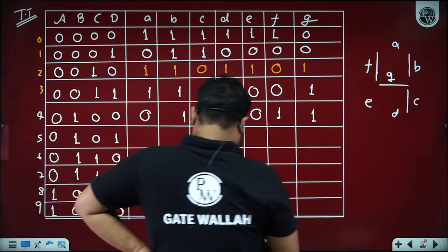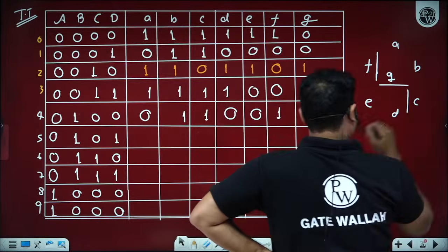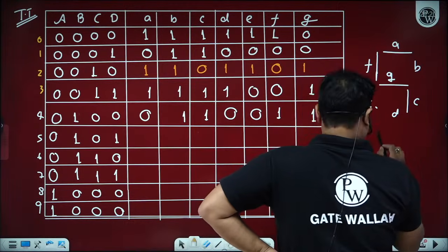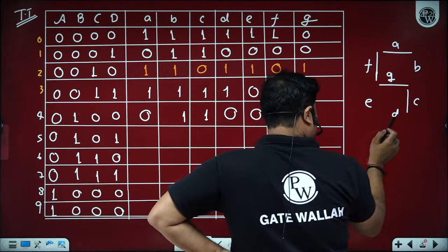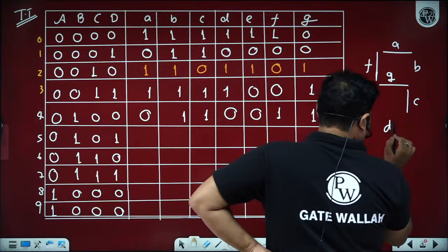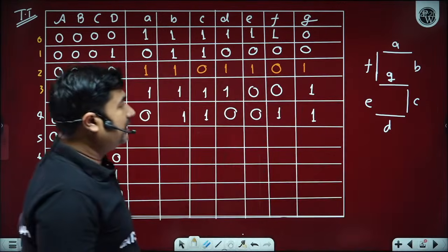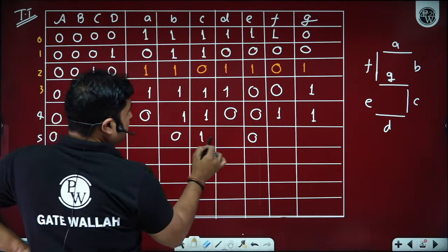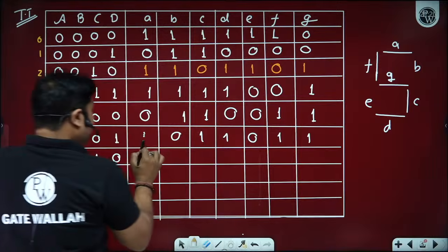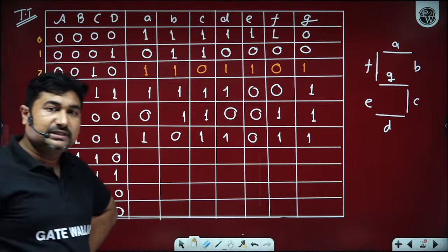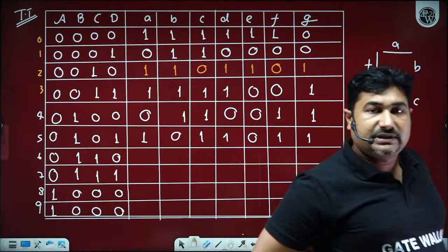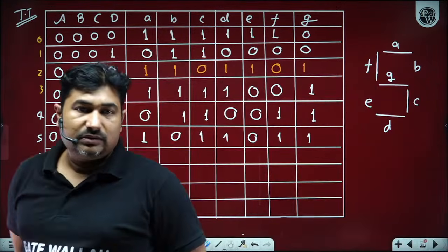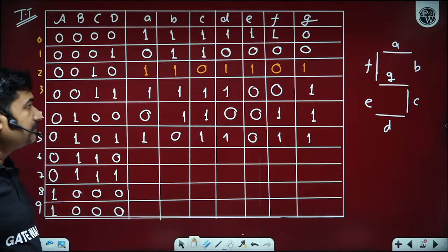To display 5, sir, to display 5, only B and E need to be low. Rest all are high. How many of you able to understand up to this part, Betaji? Please let me know by writing in the comment section. Is it okay now? Great.